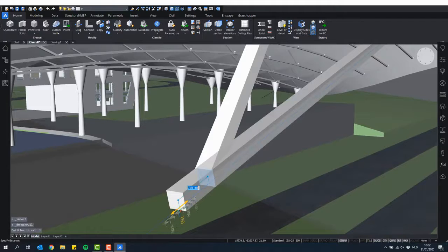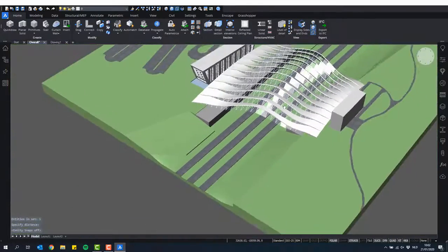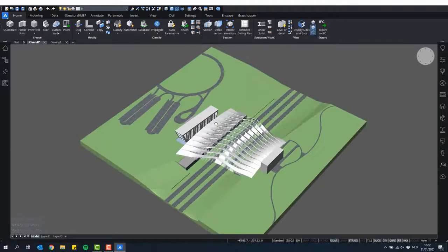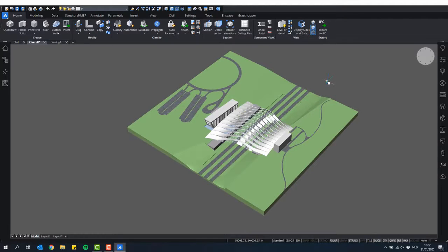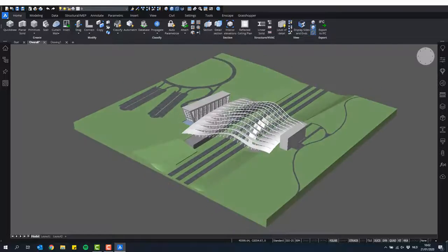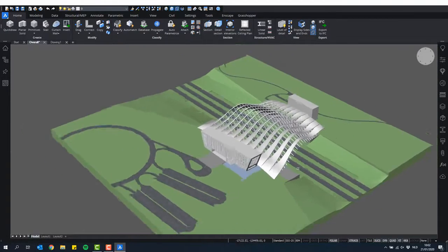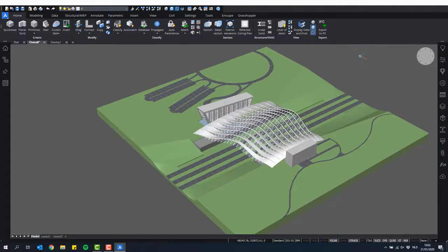But I can do any kind of direct modeling operation on this. I can push-pull this. I can classify this as members or beams. But the important part to remember is that you can model anything and apply any kind of information to it. So you don't need to predefine everything up front. You can always model everything freely and assign information to it later, or import geometry and enrich the information in there, whether this imported geometry is from IFC or Rhino or whatever.